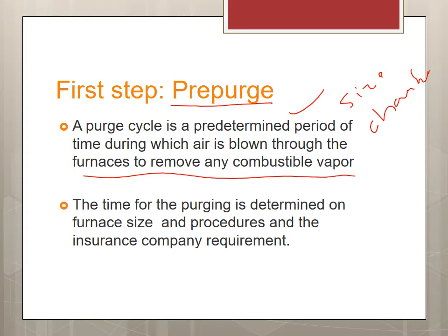The time is based on the size of the furnace, and is also dictated by the insurance company, to make sure that once we pump fuel there, it will go along with the sequence of operation. It's not going to just combust. Probably you have noticed that the chamber gets really hot, and sometimes if it's hot enough, as soon as we pump some fuel in there, it will just fire up, and that's not really desirable. So it's a good way to know that the chamber is ready, and when we start our firing procedure, it's not going to ignite by itself. That's the purpose of the pre-purging.